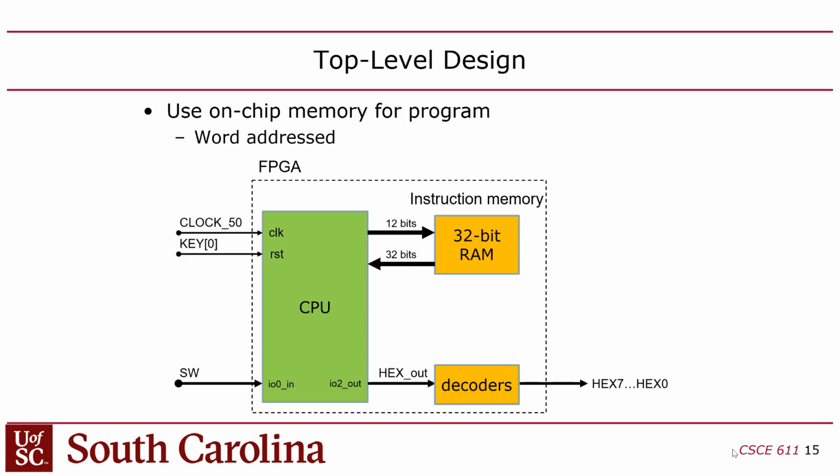Okay? And then the switches, there's 18 switches, those will come in. And then the only thing coming out is the 56 bits of the 8 7-segment hex displays. Now, if you don't have that, the compiler will optimize your entire design away. Your whole design will disappear, because the only way that the compiler will generate any hardware at all is if there is a path from the inputs to the outputs, through every circuit. It'll optimize out circuits that don't have any impact on the outside world, right? It's very sensitive to that.